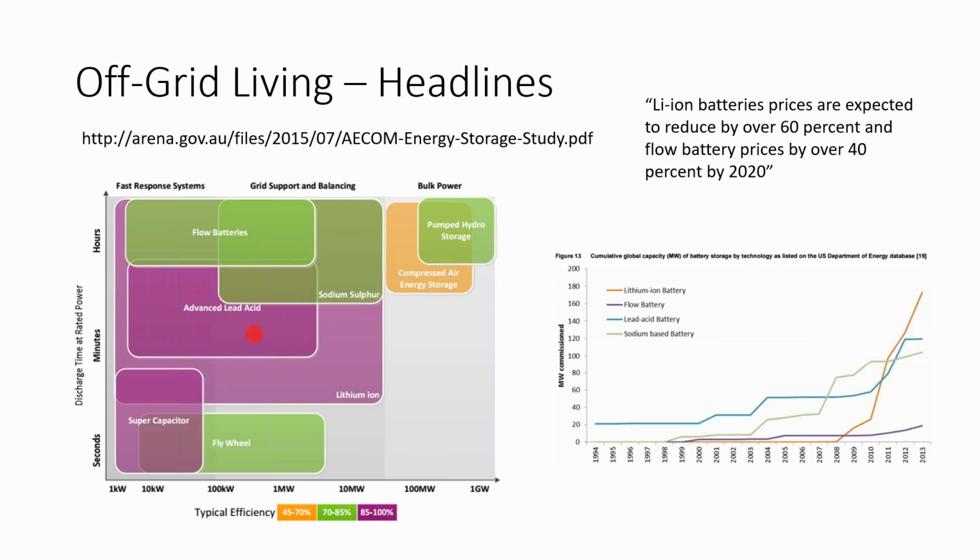It's just that you're going to have a lot more loss in the battery of a lead acid at that time. So if you're taking a lead acid battery that's rated for a 2-hour discharge cycle and you're trying to discharge it fully in half an hour instead, you might lose half of the energy in that battery from just the heat that is being generated through the cables.